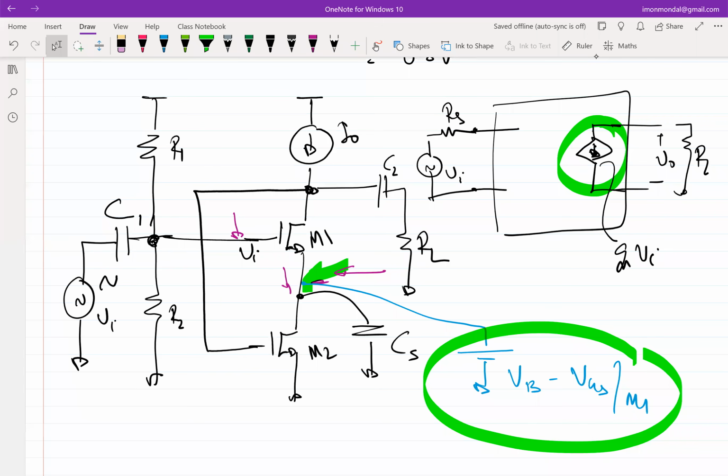Anything that is in negative feedback has some resilience. That's why you put in negative feedback, right? In the last assignment, I think I had asked you to see what is the output resistance with and without negative feedback. I'm sure you must have seen that when you didn't have negative feedback, the output resistance was very high, right? It was only capacitive, which means that at low frequencies it is infinite. But when you had negative feedback, it was quite low. It was of the order of 1 over gm, or 1 over gm times R times gm, something like that. That is not by fluke. That is by design. Why?